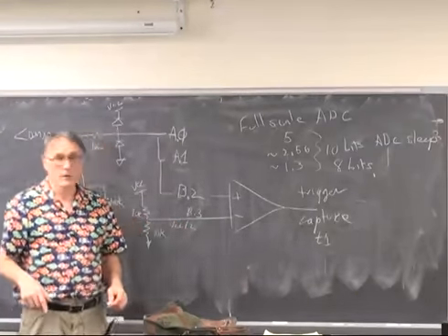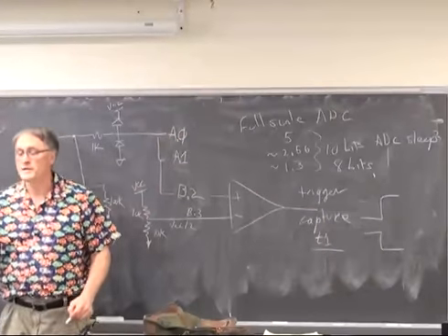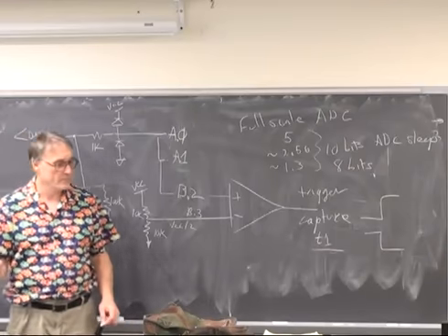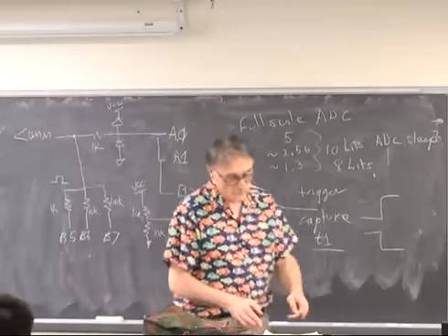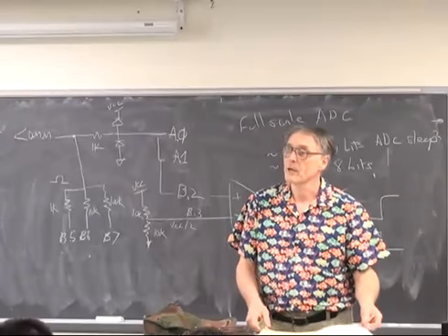So let's talk about timer 1. Because timer 1 now is the timer which has the capture feature. It has the ability to detect a rise, a fall, or a toggle on a given input bit, and to store the time of that transition in a special register. Yeah, comment? Question? Yeah.